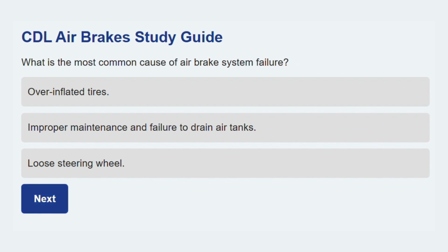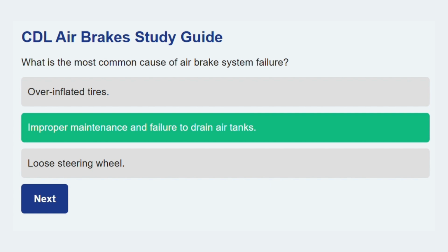Okay, what's after this? What is the most common cause of air brake system failure? Improper maintenance and failure to drain air tanks. Neglecting regular maintenance and draining can lead to component damage and system malfunction.